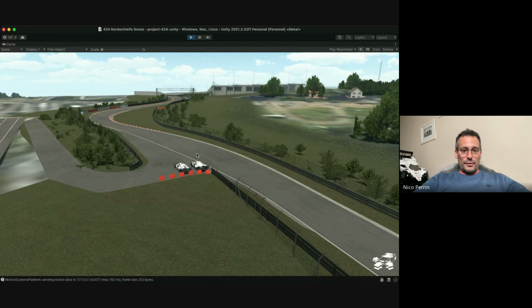We're going to park the car here in this little space that exists at the Nordschleife. In fact, this is the same scenario we did with the Neo EP9 when I was working there 7 years ago. We put the car there to start the lap. The reason is it's 1, 2, 3 corners before the start-finish line. And for an electric car, we don't want to do a full lap before we start the real lap because the battery energy is just for one lap.